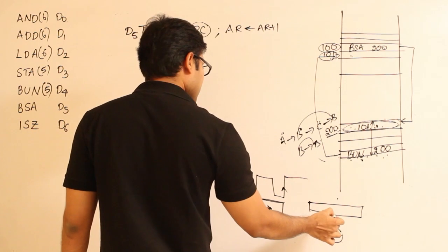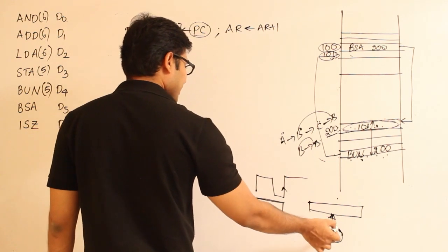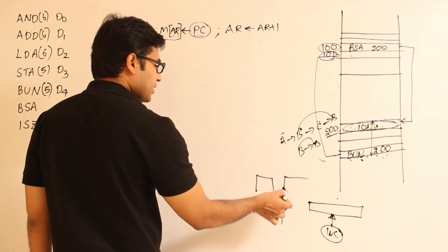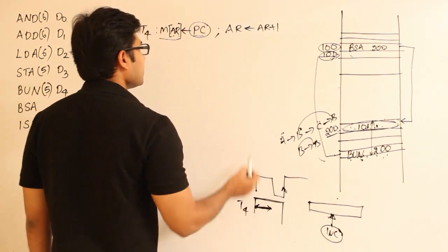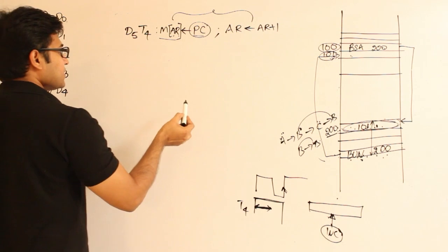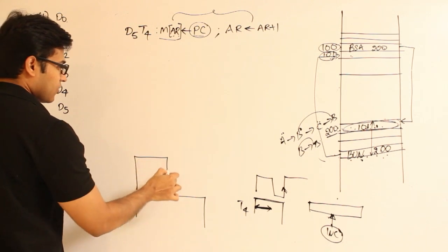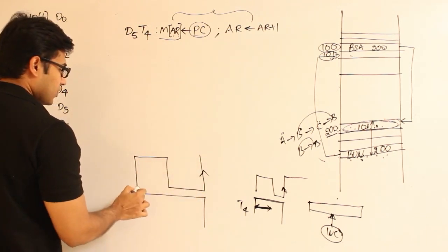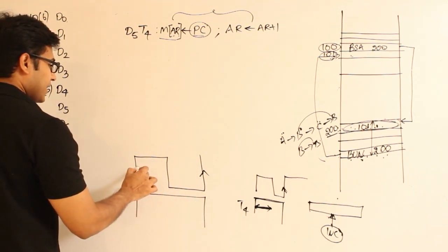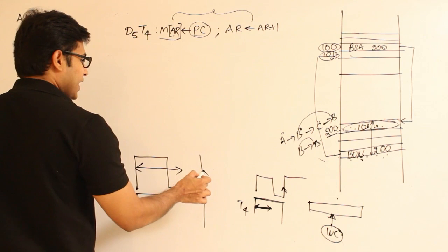So the increment is also positive edge triggered, right? So when I give this particular control signal 1, the increment is going to happen only at this point. By that time the present value of AR has already been used. Therefore I can put both these operations in the same cycle. Are you getting this? See, what I mean to say is, if you are having this clock like this, T4 like this, then corresponding to this clock, this is the T4. Now I am saying that the access of memory using AR will be completed sooner, right? And the increment will happen here.